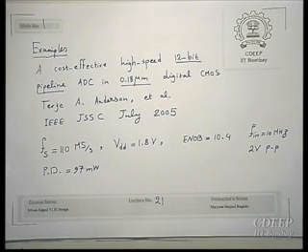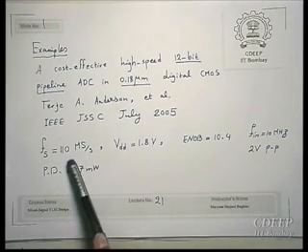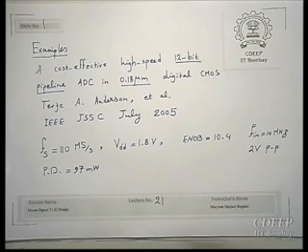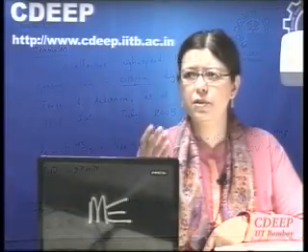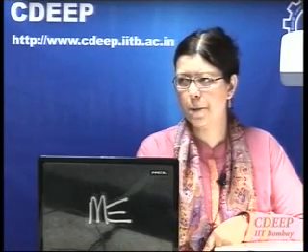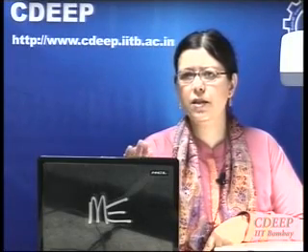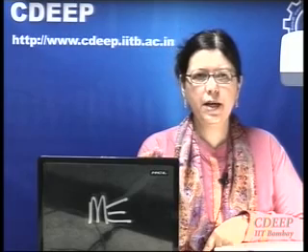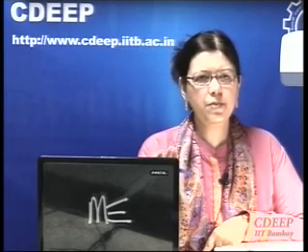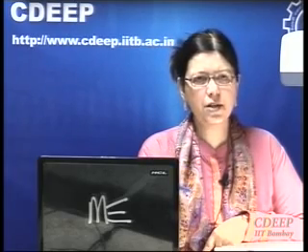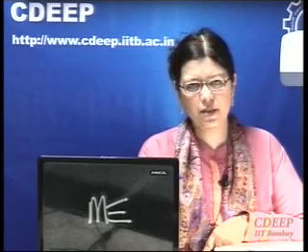It can reach up to 100 megasample per second, but you may use it for some cases at 1 megasample per second. Therefore, you may not need everything, including the Opamp, to have the settling time you need for 100 megasample per second. Why unnecessarily consume power? Therefore, they have a switch capacitor based current reference generator which scales the power according to the sampling rate. And this helps to avoid extra power dissipation.